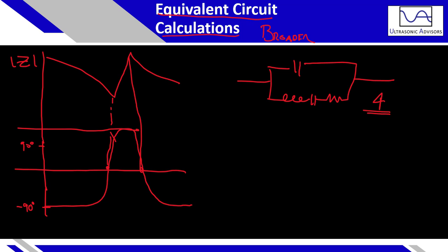So the first very important frequency that we're going to be using is the resonance frequency. The resonant frequency is determined by this circuit, and specifically where the inductor and capacitor for this branch are at resonance. Now, contrary to a common understanding, it's not the frequency of minimum admittance, although that is very close to the actual resonant frequency. What you will find is that the frequency of resonance is the frequency of maximum power dissipation in this circuit.